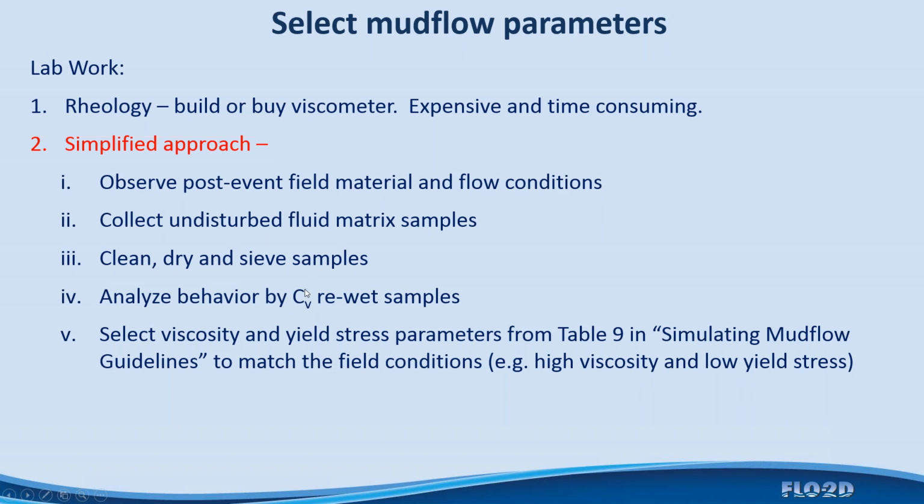Then analyze the behavior by starting with one concentration. The way that you do that is you weigh the sample dry, and you add a certain amount of water to it, either by volume or by weight. You compute the concentration by weight. You can convert that to concentration by volume. And then you have one point in your viscosity versus yield stress behavior